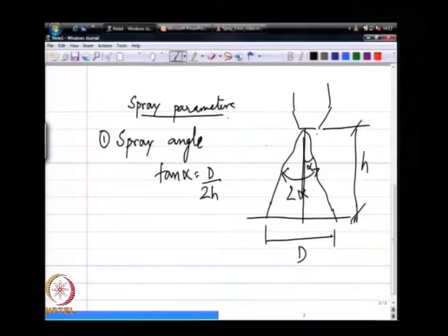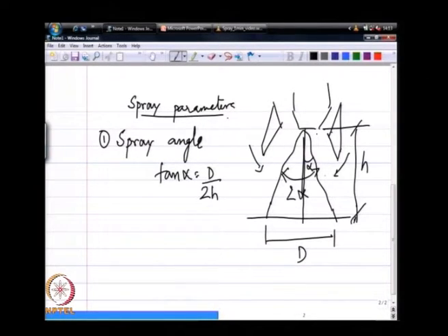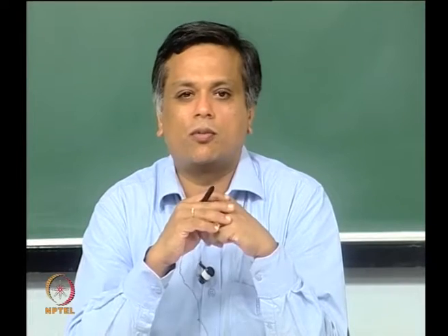Another one is to just bring a couple of blades of a protractor towards them, and when these appear parallel to the human eye, the angle between the protractor blades is equal to the angle over which the spray happens. So, these are common ways of measuring the spray angle.